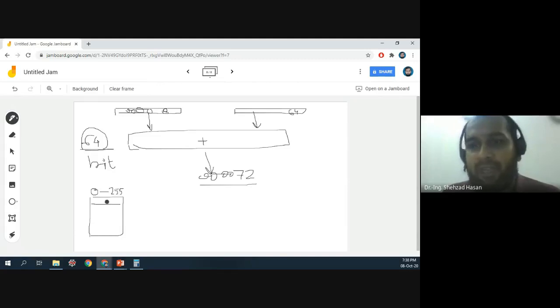So it's an image having many pixels, and you want to increase that pixel intensity by a constant like say 40. So every pixel's intensity should be added with 40 and then stored back. How can you do that in such an adder? So what you're going to do is you're going to take the first pixel, add 40 to it, and store it back. Second pixel, add 40 to it. So you're doing one byte at a time, even though what you have is a 64-bit adder with you.